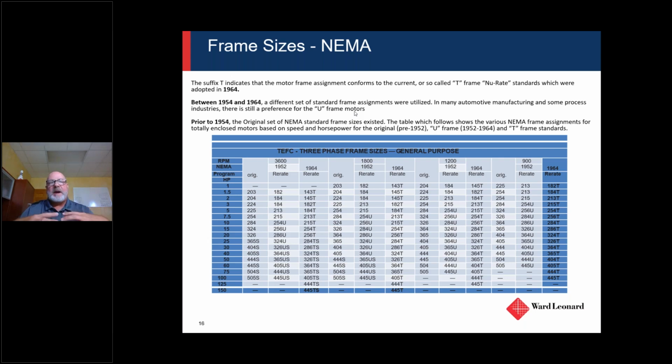So all of the manufacturers, because pre-NEMA, it was very difficult to apply different motors to different things, right? Because everybody was dimensionally different. So NEMA got together and said, well, we're going to standardize on a frame size. It just makes things much simpler. So they did. That went through a few variations, and you can read that up here.